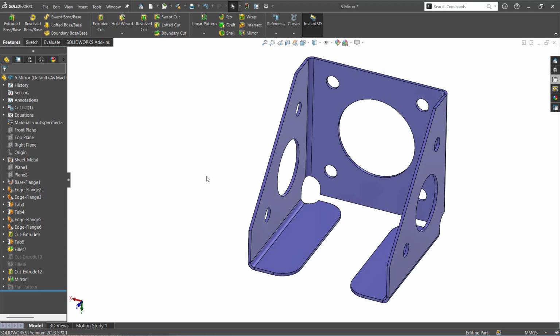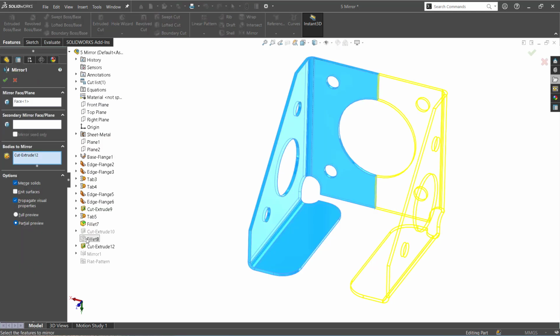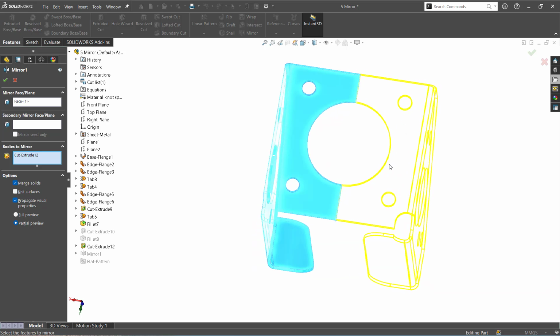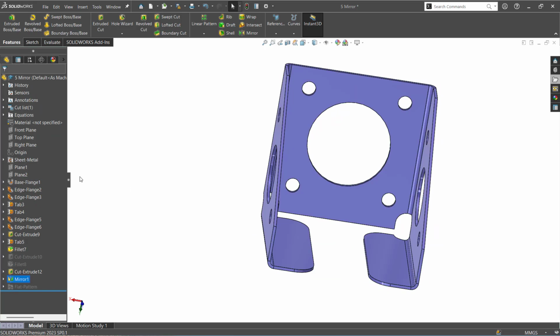And what about the knit surfaces? If you are using the surfaces method, it acts the same. So if you have 2 surfaces, if you activate knit surface, it will create a single surface. It will try to stitch them. Yes, got it. Now my requirement is I would like to have everything, but I don't want these 2 small holes. What do we do now?